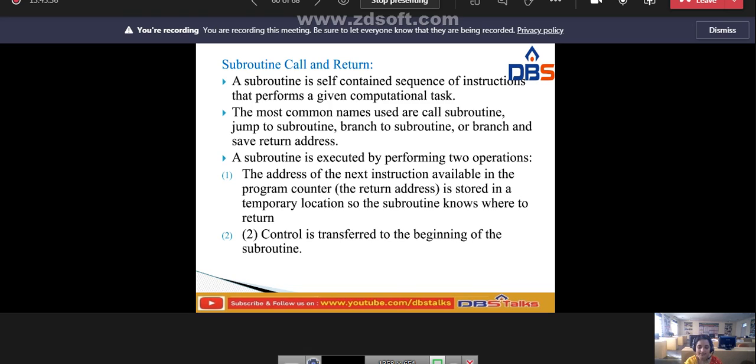The last instruction of every subroutine, commonly called return from subroutine, transfers the return address from the temporary location into the program counter. Different computers use different temporary locations for storing a return address. The advantage of using the stack for the return address is that when a succession of subroutines is called, sequential return addresses can be pushed into the stack.